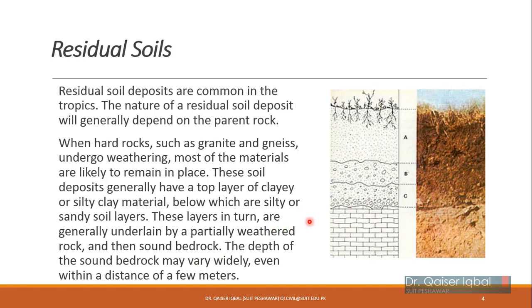Okay, this kind of deposit is commonly formed in the Swat region. You may observe when you excavate over there that at the top you will have clay. After a few feet you will start discovering silt and sand, and when you dig further you will start discovering fragmented pieces of rock, fractured rock, and then when you excavate further you will reach the sound rock. So that will basically be an indication of residual soil over there.